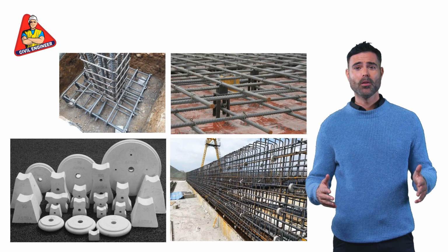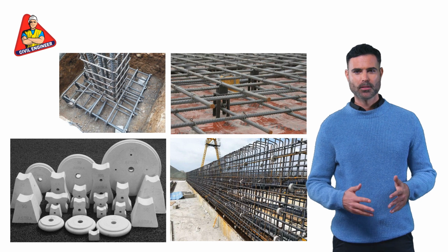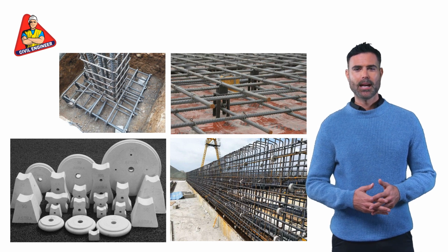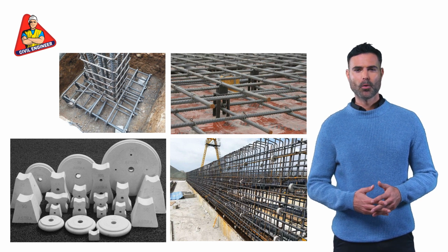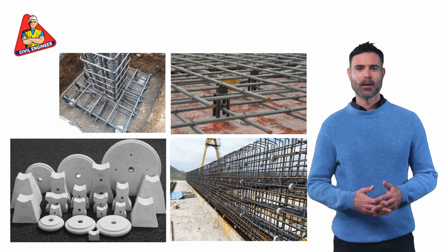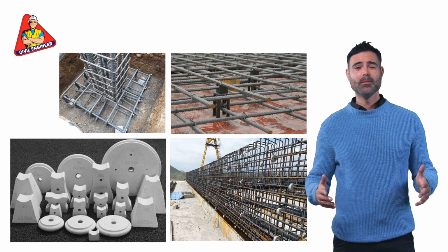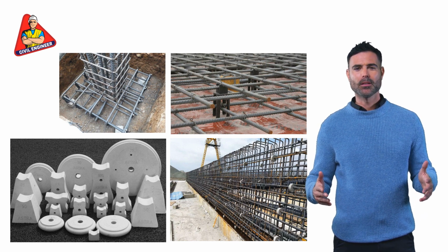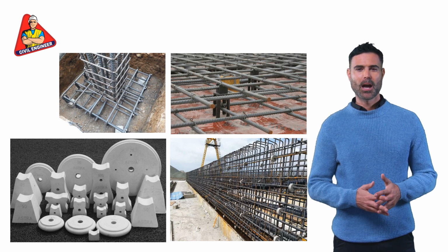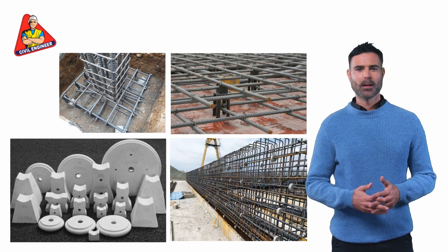Cover requirements differ across standards, but generally fall within common thresholds. According to AS 3600, for structures in A1 exposure conditions, mild indoor environments, slabs require a minimum of 20 mm, beams between 25-40 mm, and columns 40 mm. IS 456 maintains similar values, while ACI 318 may prescribe 50 mm or more for members exposed to weather or ground. Always refer to the exposure classification, fire resistance requirement, and structural type to determine the final cover.